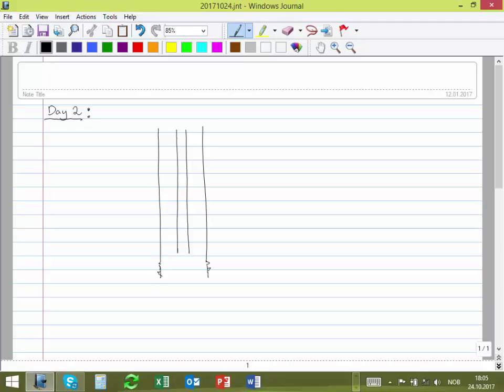Okay, remember that in reality when you drill you actually have a lot of concentric pieces of pipe, casings, that go from bigger to smaller and smaller, and they depend on the pressure envelope that you have, to be between the hydraulic pressure and also the fracture pressure. Okay, to avoid that you get fluids inside the wellbore, but also to avoid that you actually frack and break the formation. That's the reason why you have all of these tubulars. So here I'm just neglecting all of that, and I'm just putting the part that concerns production. That is the production casing, the innermost casing, and then the tubing.